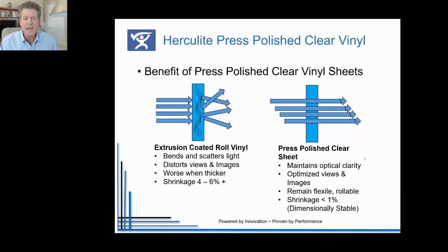So with these 5 different parameters, this is what each sheet has to go through in our process. The first is lamination quality, where we take the sheets and pull them to make sure that we don't have any separation. And we take a cross section and magnify it to make sure that the lamination is good across the sheet.